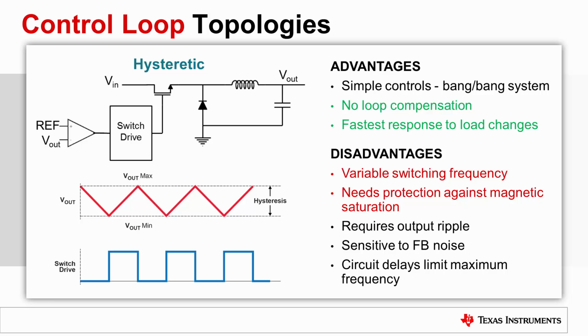Despite the benefit of fast transient response, some systems cannot handle a variable switching frequency power supply. Customers may have tight frequency spectrum windows for switching power supplies. If this is the case, then another control method that is synchronized to a clock should be explored.